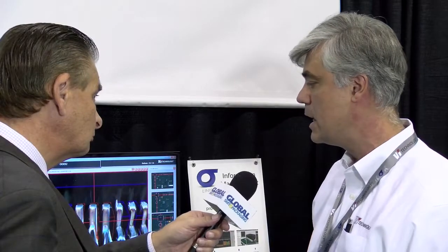The nice thing about this, which a lot of people don't realize, is that there is a lot of technology behind all this. It sounds easy to make it stop, but we have to save all the images from SPI and all the images from AOI temporarily, of course, because we may want to prune them later so that we're not storing terabytes worth of data. And we have to have communication between the SPI and AOI, which is possible by having our pieces of equipment in the line, and that allows us to do that.